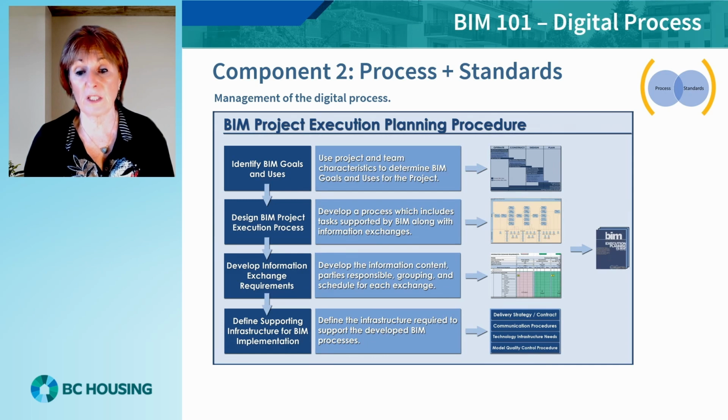This is all recorded in a living document, the BIM execution plan, which sets out who is going to do what, when, how, and where, i.e. in which model the information can be found. Management of the data and any duplication is critical. Auditing is required to ensure that the BIM execution plan is being followed and the data is fit for purpose.